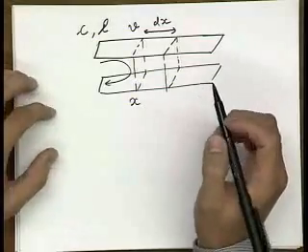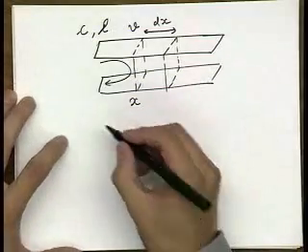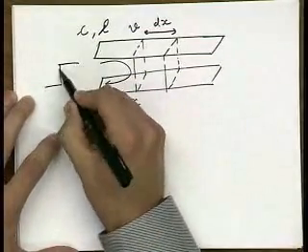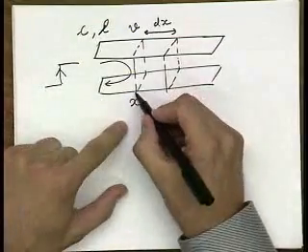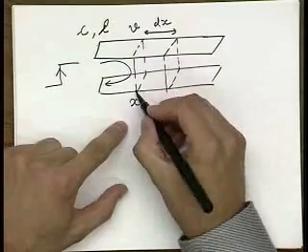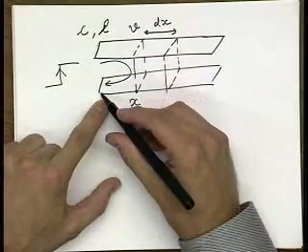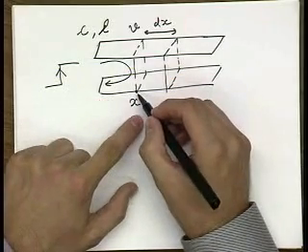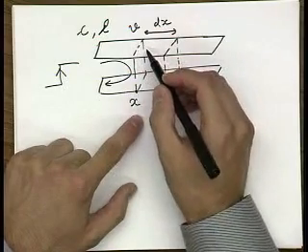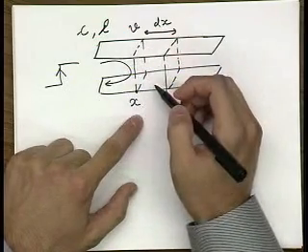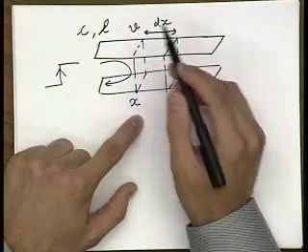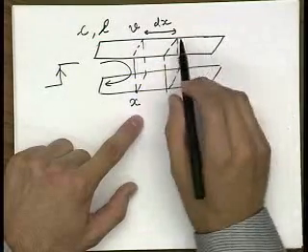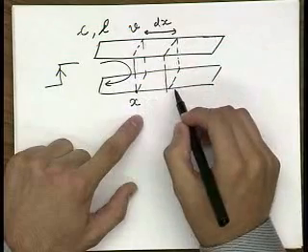So now let's assume that we start with a step response at the input, and that we observe this point x away from the input, and assume that a sufficient amount of time has elapsed such that we have voltage V over here and that we have no current to the right of this point x.